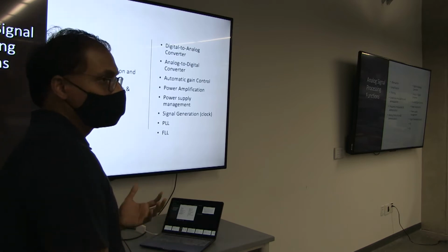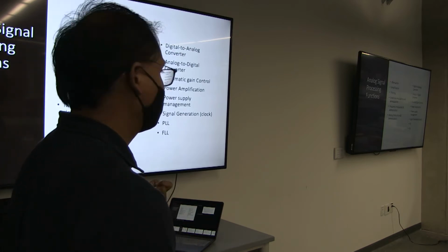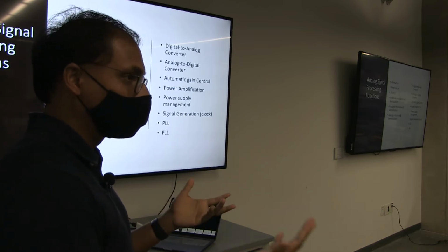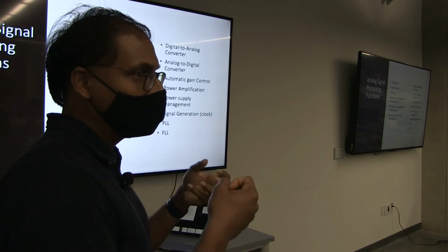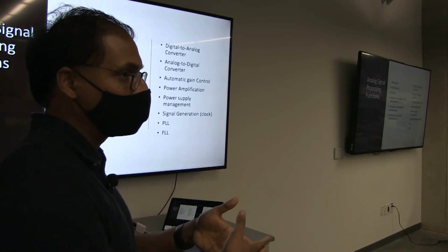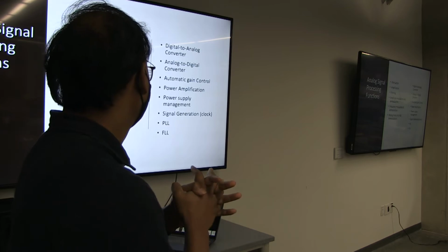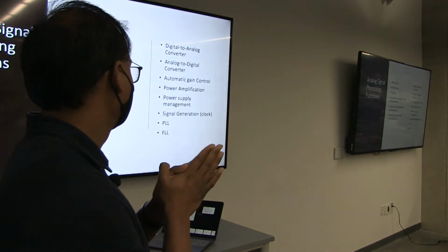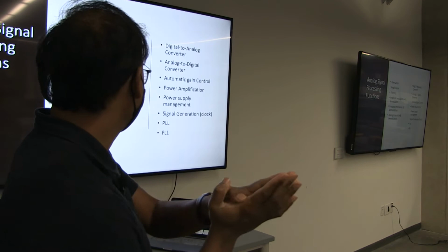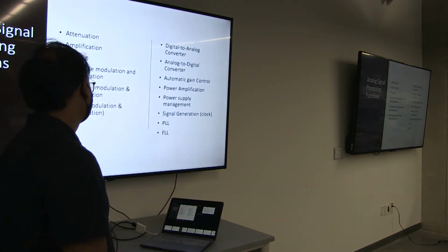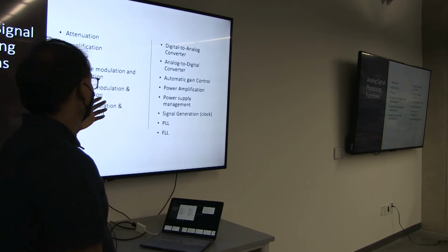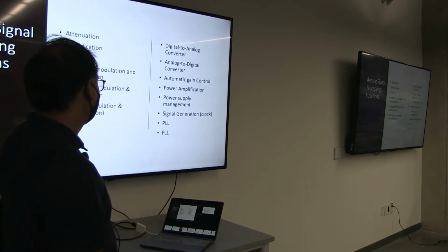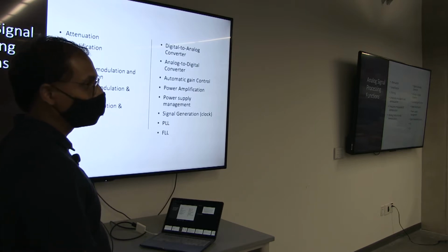Filtering is another very important tool at our hand. For example, if we talk about a mobile phone, we have a lot of RF spectrum around us. There will be RF filters at the input of the antenna to select the signal of interest or the band of interest, and further there will be modulation in the signal chain. It can be either amplitude modulation or frequency modulation, and currently these can be done in the digital or analog domain. In olden days we used to use analog modulation.